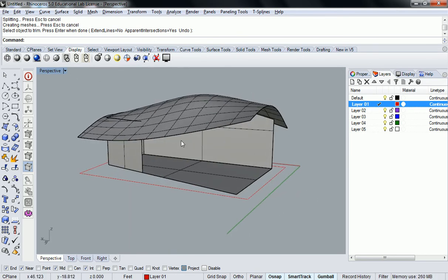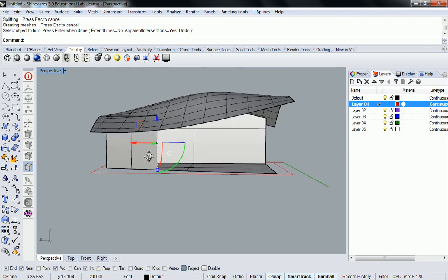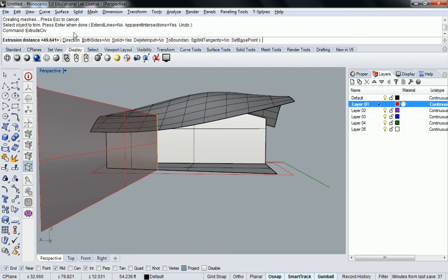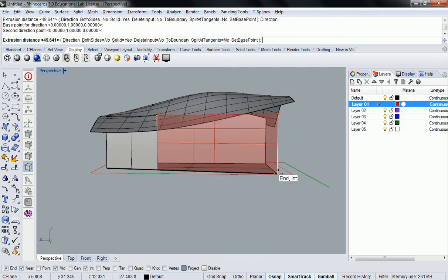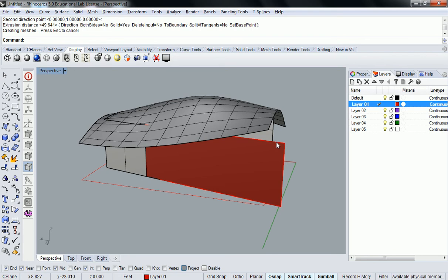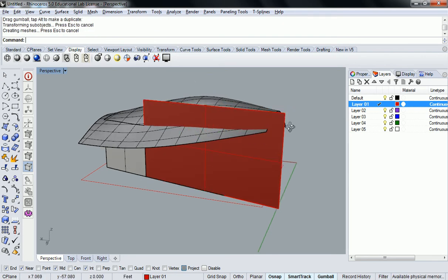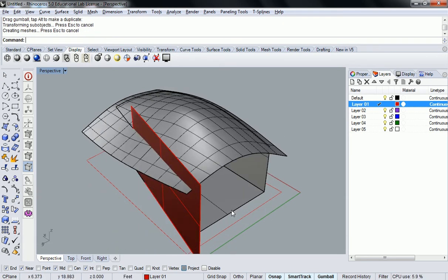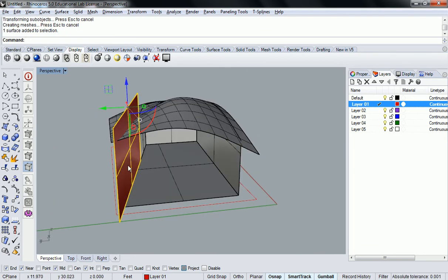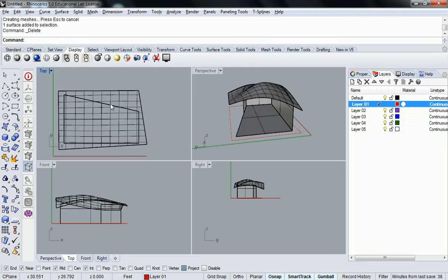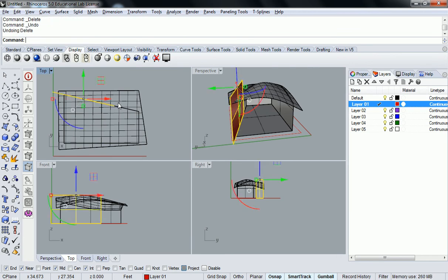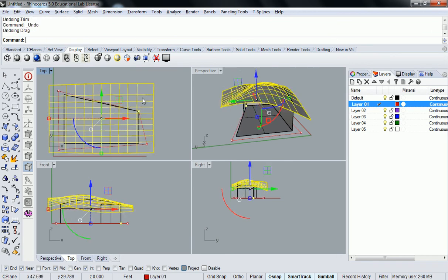The other thing that you could do, it's probably not your best option, is you can create new surfaces off of extruding these edges. So you can just say extrude curve, set the direction, go from here to there and pull it off, and then grab that one as well and yank that above, and you can use that to trim and do that just to close it off. But I think the best bet is to utilize your other views to the best of your ability, because that's going to grant you, I think, the largest and most accurate amount of control.